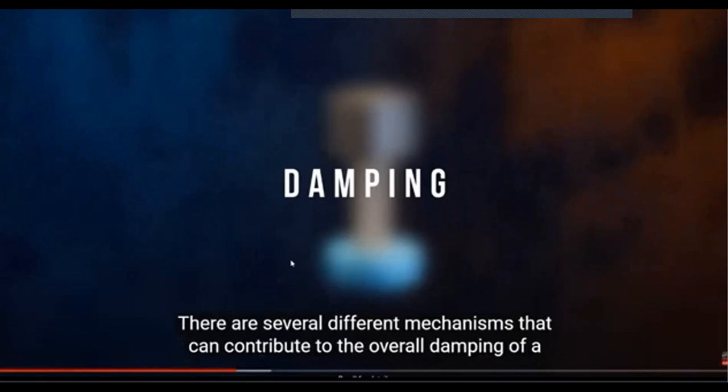We are using damping for our advantage. That means that we have something like shock absorbers when the drum is rotating. Why do we put those? Because it should be able to absorb the motion and finally damp it, so that what is desired is rotation of the drum, not vibration of the drum for the washing machine. Similarly, when we drive the car, we are expecting the car to move forward, but we also have the springs in the tire which will absorb the ups and downs or the humps of the road to make our travel smooth, and ultimately they damp it. So that's what we are using for our advantage, damping.